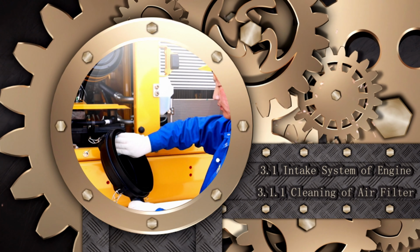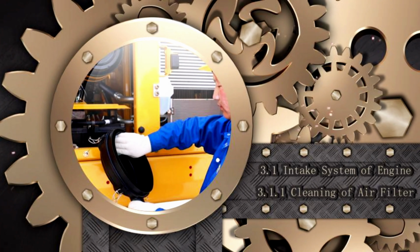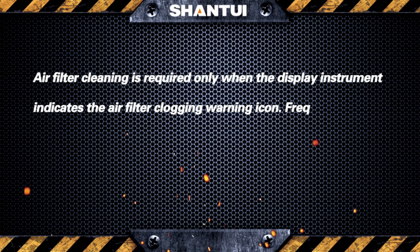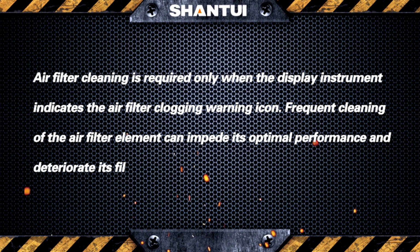Irregular maintenance of excavator. Intake system of engine. Cleaning of air filter. Air filter cleaning is required only when the display instrument indicates the air filter clogging warning icon. Frequent cleaning of the air filter element can impede its optimal performance and deteriorate its filtering efficiency.